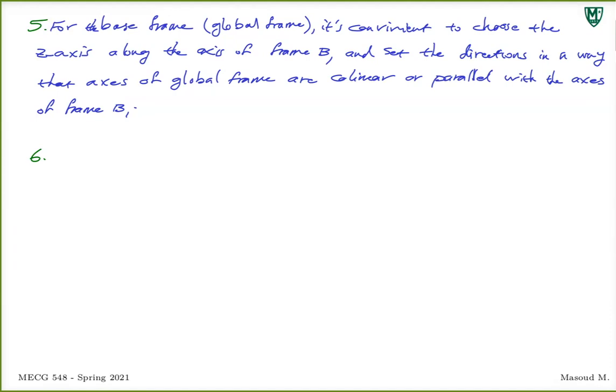Now, if I don't give you the gripper or whatever is the end part, and I just give you the manipulator part, you're going to end up having a link at the end, and you need to know what the final joint is, because the type of joint determines where the z-axis is. The z-axis is always parallel to that joint's axis. So when you get to the final frame, you have to know something about the joint attached to the end of the final frame, connecting that frame to the next possible frame or whatever comes after that.